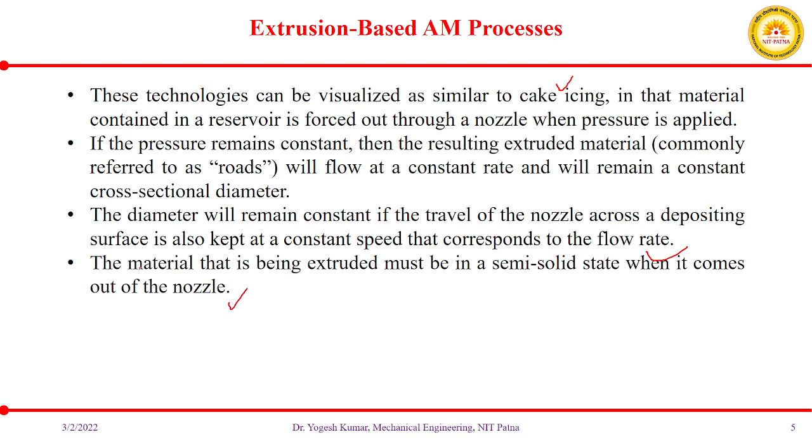This heating arrangement may be inside your nozzle, or before coming into the nozzle, the material must be in a semi-solid state. Normally, some heating arrangement is provided when this material is going inside your nozzle. Okay, so the heating arrangement is itself kept inside your nozzle.